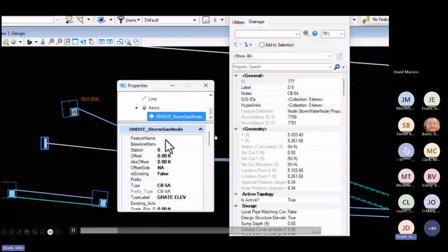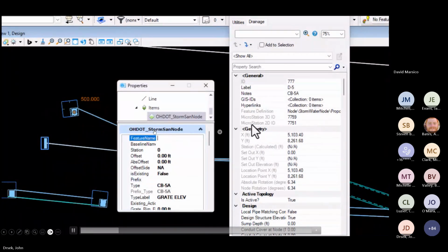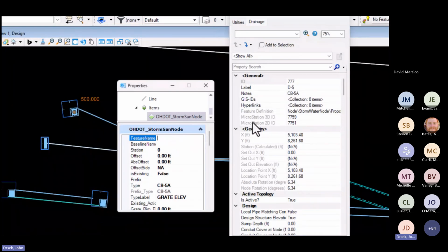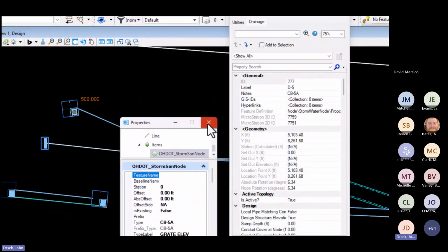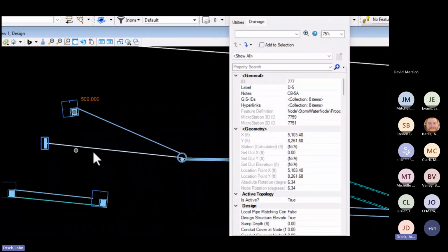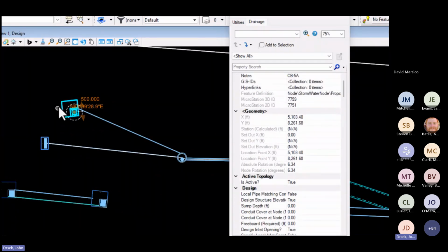I do want to mention though, you don't want to try to edit from the item type dialog directly, because once you run the sync tool, it's going to overwrite that, and there's no back connection to the feature, right? All those item type properties are just going to get filled out by pulling data. There's no pushback. So that's not something you want to change.